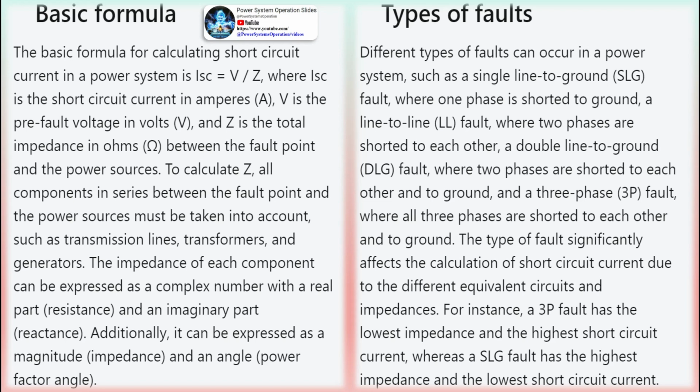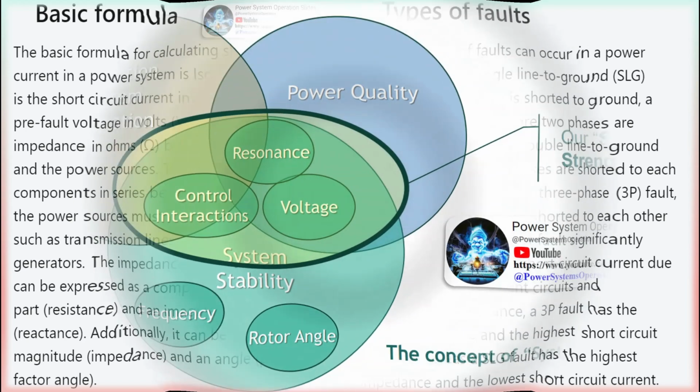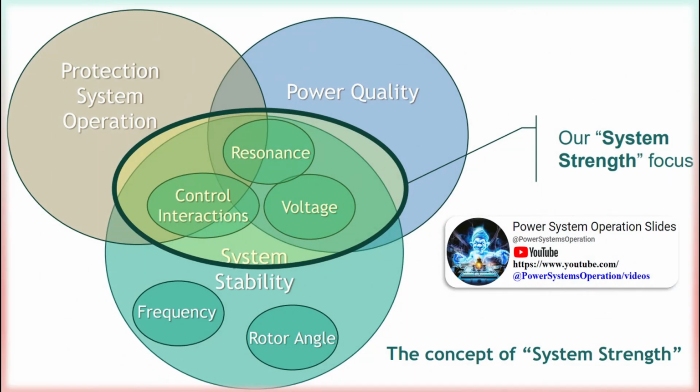A short-circuit analysis will help to ensure that personnel and equipment are protected by establishing proper interrupting ratings of protective devices, circuit breakers and fuses. If an electrical fault exceeds the interrupting rating of the protective device, the consequences can be devastating. It can be a serious threat to human life and is capable of causing injury, extensive equipment damage, and costly downtime. On large systems, short-circuit analysis is required to determine both the switchgear ratings and the relay settings.